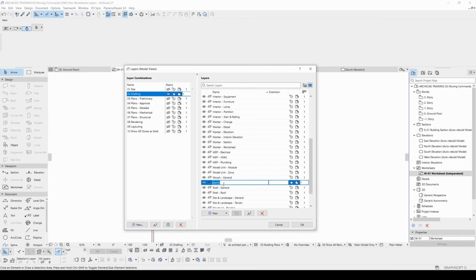So we will make this visible. To do it, we will click this sketch and click this eye. Or you can open this eye, and as you can see, the drafting selected. After that, you will hit this update status. Then we will hit OK.